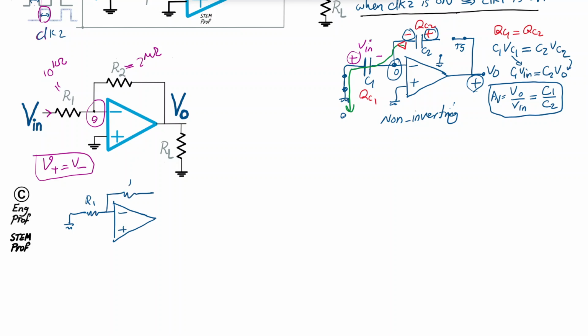this. So here we have R2, R1, Vout, and then we have, let's say, the connection of R1 to Vin, which this resistor doesn't matter, it's only for matching, because for an ideal op-amp there is practically zero current going through the input terminal of the op-amp because of practically infinite impedance. So Vin appears here at the positive terminal, then because of the virtual short Vin appears here, then there are R2 and R1 effectively in series.